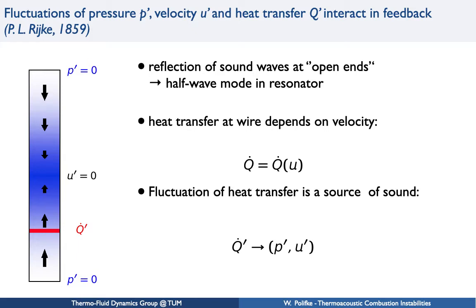With the hot wire, we also have heat transfer. Depending on the flow rate of the gas across the wire, you have more or less transfer of heat from the heated wire to the gas. And then the last statement here on the slide is something that needs a bit more explanation perhaps. Fluctuation of heat transfer is a source of sound. Why is that? Well, think of a loudspeaker.